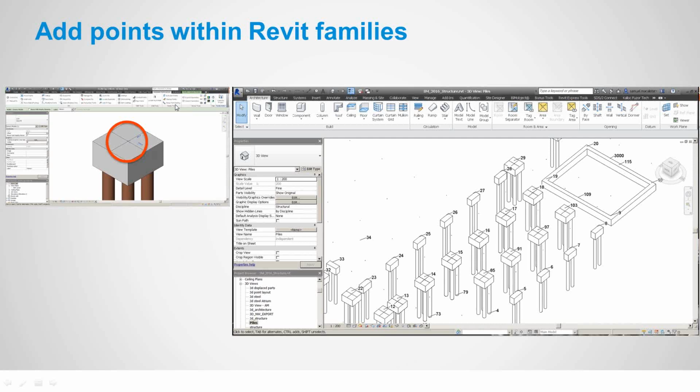We still have access to the point layout tools, and we can add a point to the center of that pile cap. Then when we bring it back into our Revit project environment and tag it all, I don't need to manually place those points. They're always going to read at the center of those pile caps. So there's several ways you can populate the control points within your model.